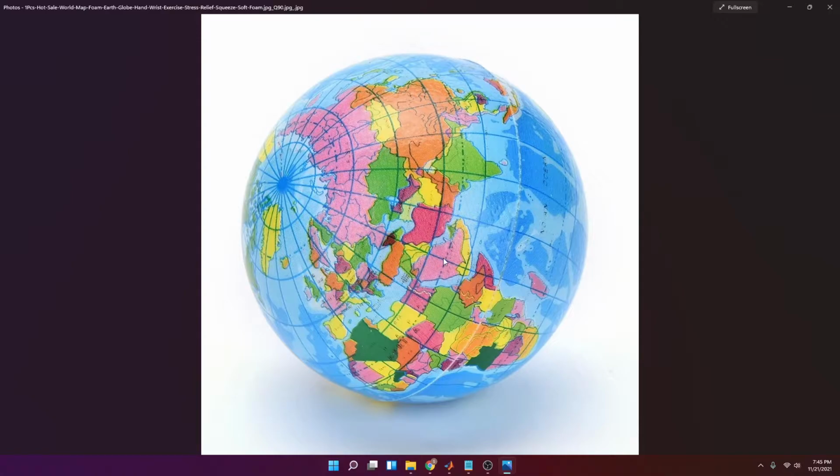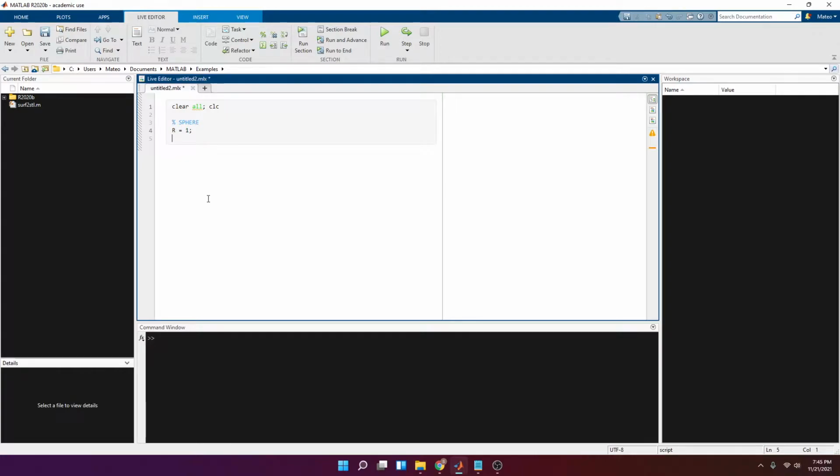The axis of this geometry is going to be along the two singularities. So the x and y coordinates for all the points in the singularity cross-section are going to be 0. Just want to point that out before moving forward. Okay, so having said that, I'm going to set the number of cross-sections that we want, and let's say 10 for now. And then the number of points per cross-section, so let's call them nodes.